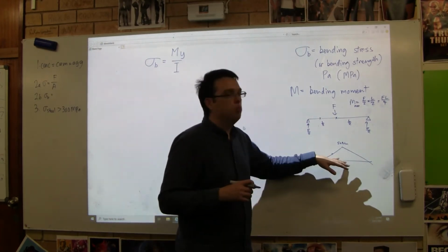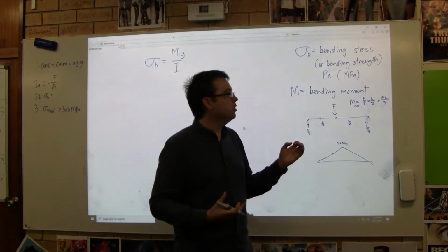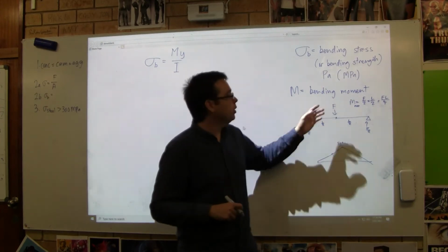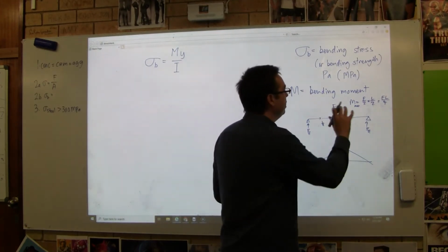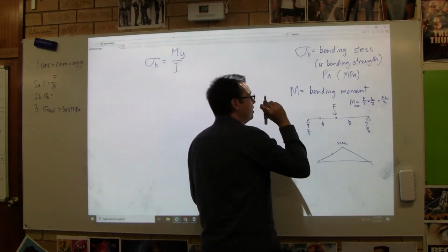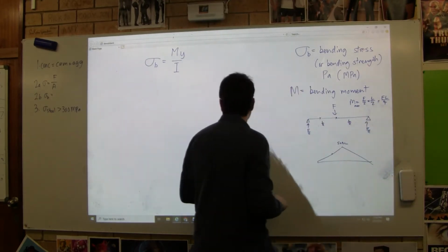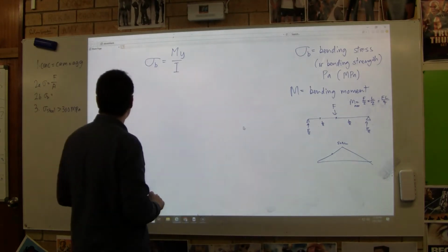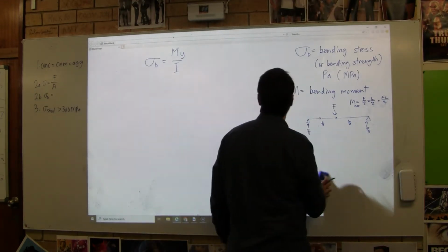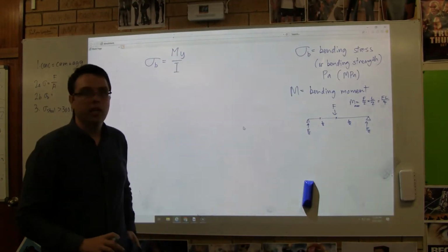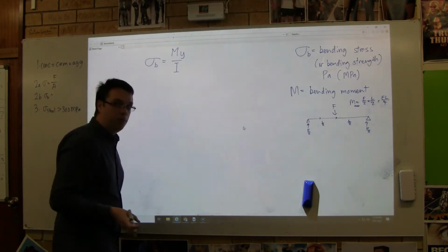Now, this diagram looks very different depending on different load conditions. But for the moment, we just want to use a simple diagram, right? And so for a simple single symmetrical load, we can use this rule, M equals FL on 4. Okay, the next thing we want to do is find Y, right? Now there's a Norah Jones song called Why, and then there's a Sesame Street version of that, but we don't have time for that.